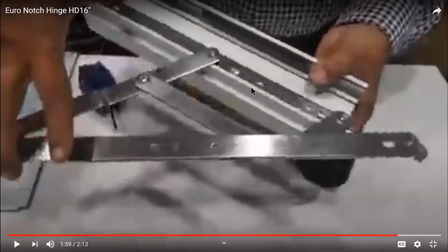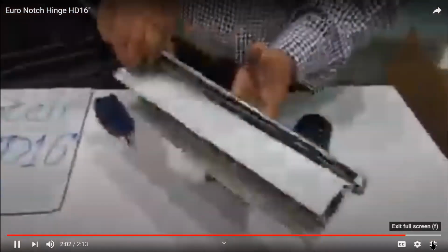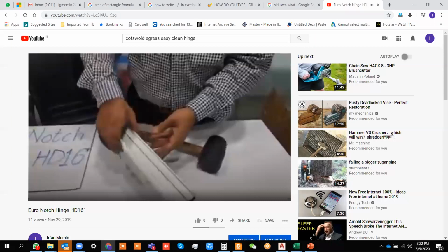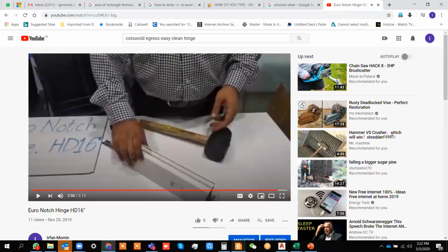Normally what happens with your other arms, this groove is required to be machined and packers are required to be used. With the help of the Euro arm, you don't need to machine anything. Simply put the arm inside the sash frame, and without machining anything, it's applicable. It could be used in top hung as well as side hung. I will show you the chart now, and it's designed in a specific way.